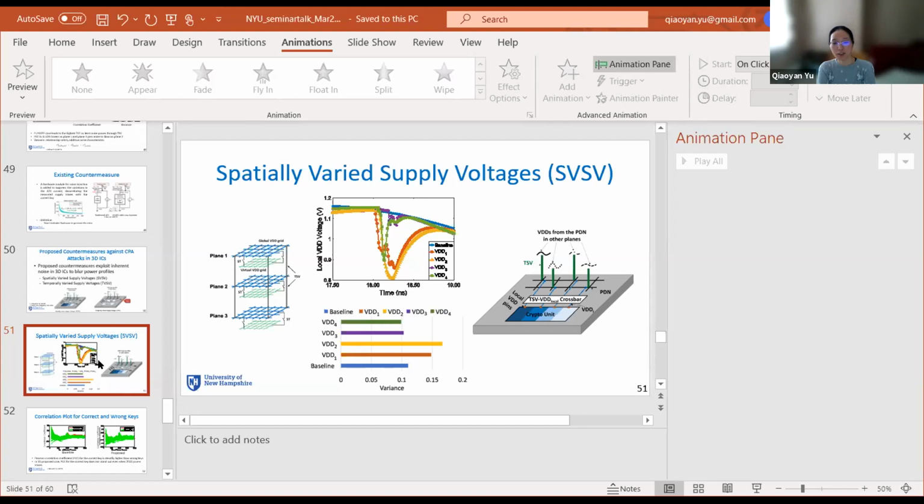Another thing I would share is that we also tried to get 3D FPGAs to perform a more realistic performance evaluation. We really tried, but currently the 3D FPGA boards are mainly not stacked like what we want, a TSV based stack. Mainly they just have memory layers on one layer and the function on the bottom. So I do not find a good 3D FPGA board available, but I wish maybe someday an FPGA company could produce a really 3D stacked FPGA for us to use.